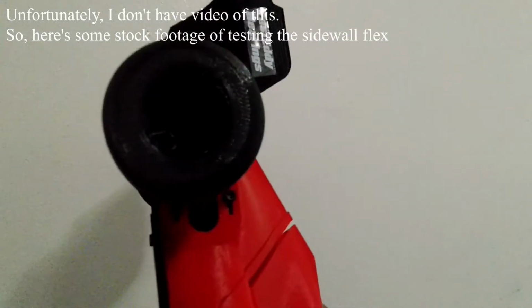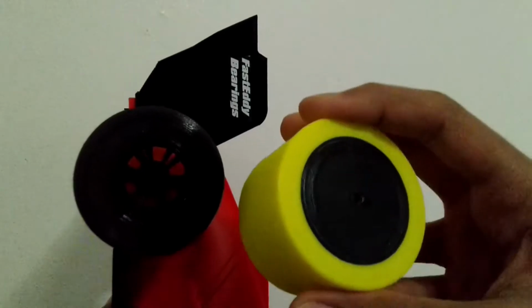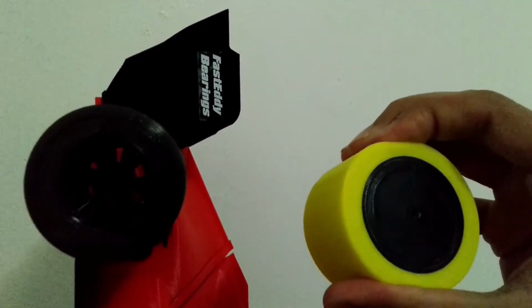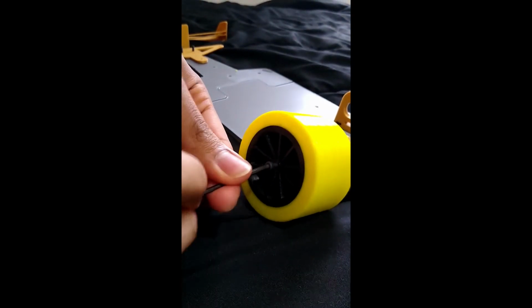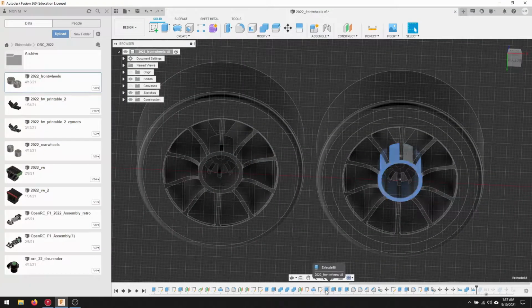See, the design I had that put the wheel bolt all the way from the outside of the rim into the axle also relied on the bolt to hold the rim in place, causing the wheel bolts to come undone the moment the wheel rotated. That's when I realized that to fit the suspension, the wheel nut design has to be the same as the original. To fix this, I went back and did a few iterations.